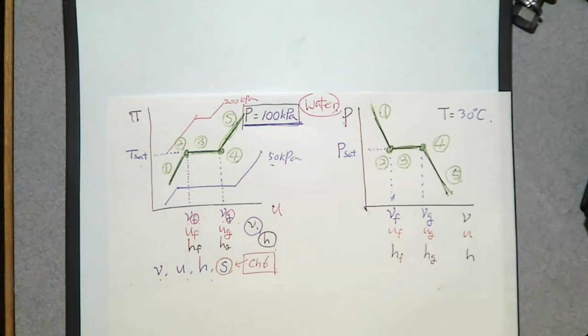No, you can use different units. It can be bar, kilopascal, atm, anything you can use, but you want to stick to one unit so as not to confuse, right? And I recommend using kilopascal, which is the most common pressure unit that we use in thermodynamics.